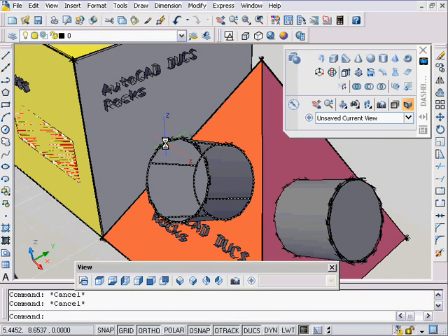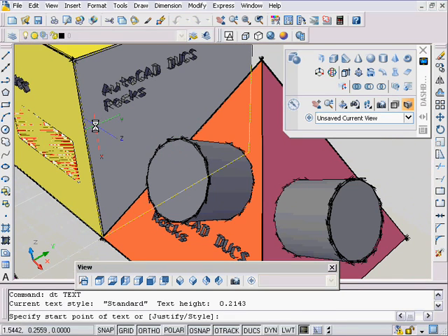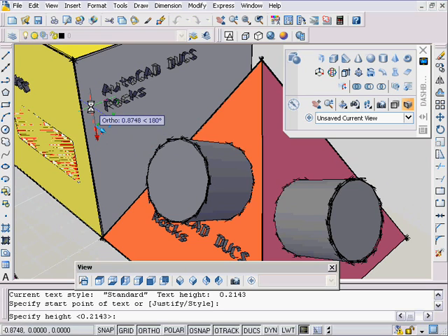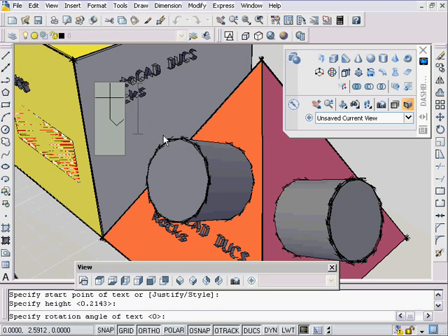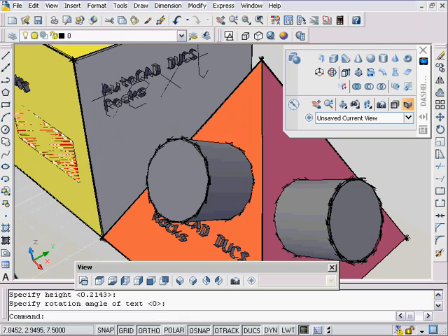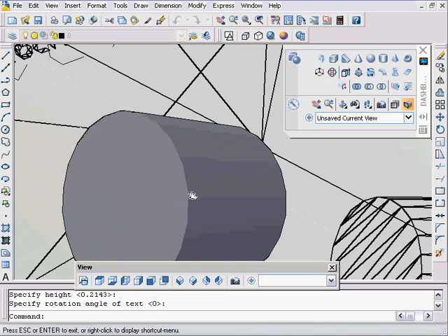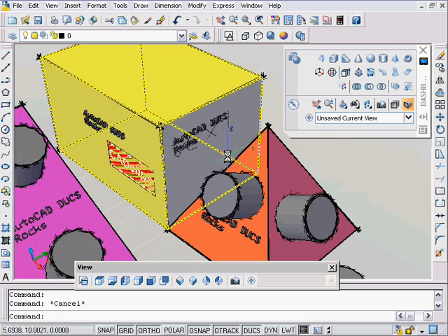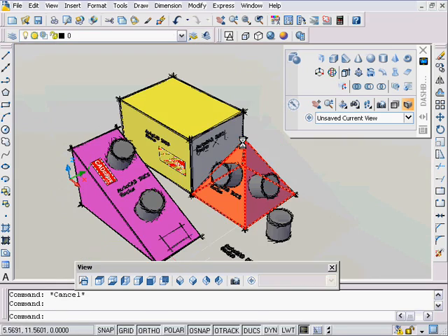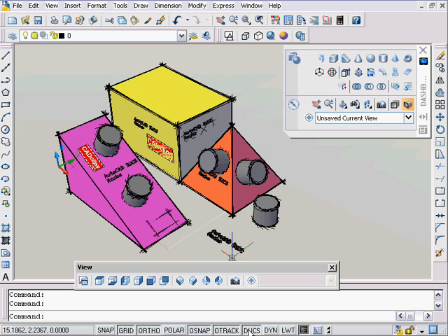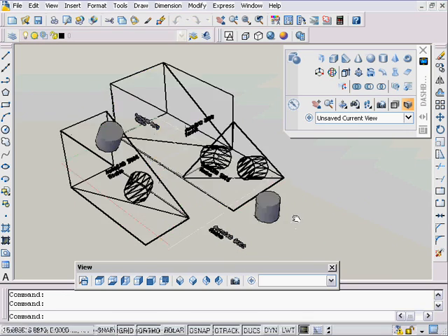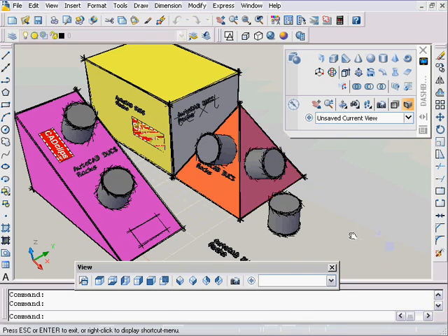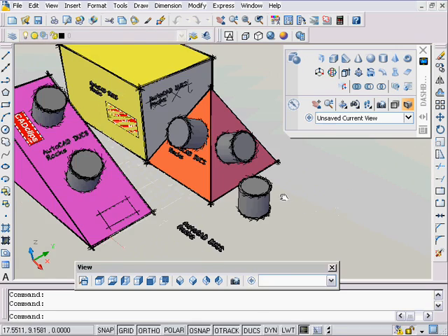Put text, even if you wanted to, maybe let's try doing the dtext command all by itself. Click on here. You can put text right on the surface by doing that. I don't know how applicable that is, but you can do that. So anytime you want to work on any surface, use your dynamic UCS. Also, if you want to get a shape, draw it over on the side somewhere, don't worry about it.